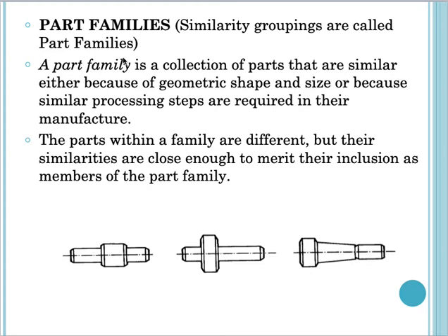Computer aided process planning involves the automatic generation of a process plan, or you can say a routing sheet, to manufacture the part. The process routing is developed by recognizing the specific attributes of the part in question and relating these attributes to the corresponding manufacturing operations.